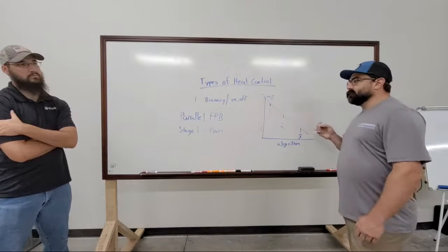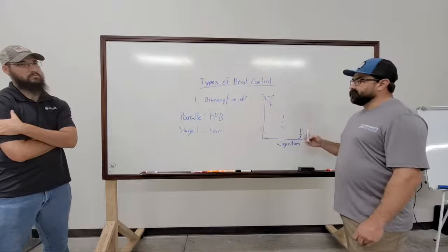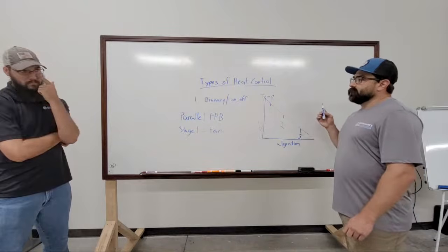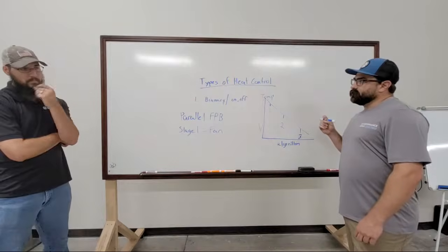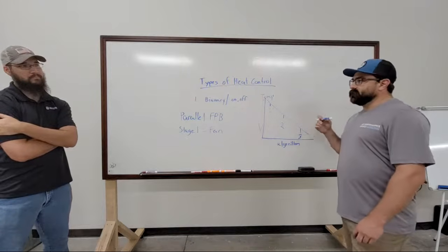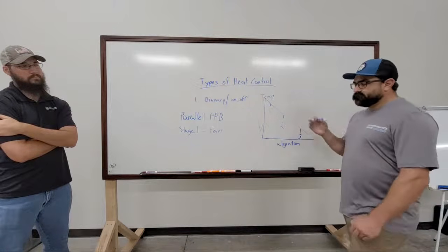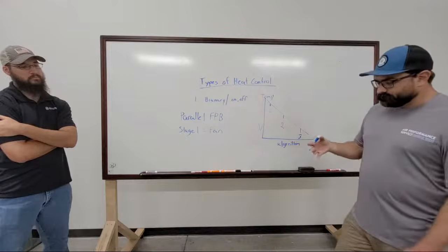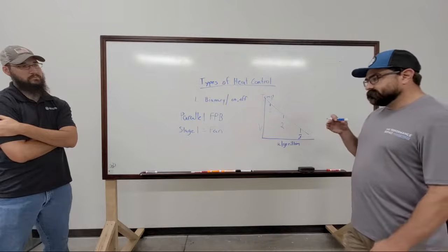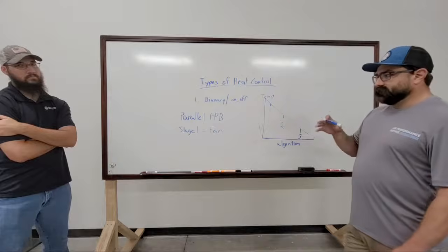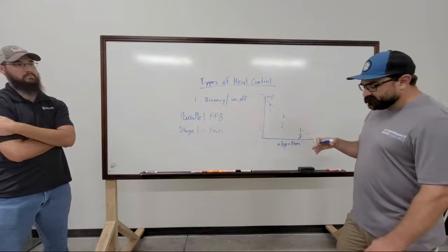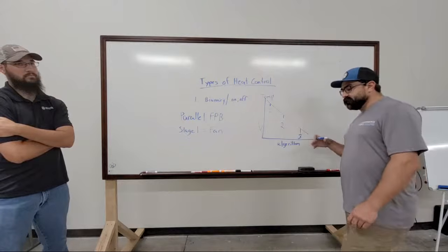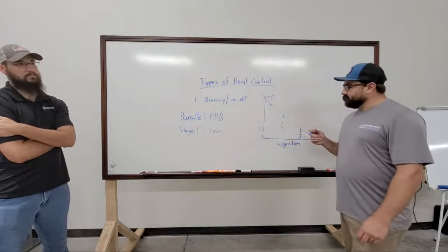One thing to note about VAV boxes, without going too far into it, a true VAV box maintains flow, whereas it appears they maintain temperature. You are really using space temperature versus set point deviation to adjust your flow set point.